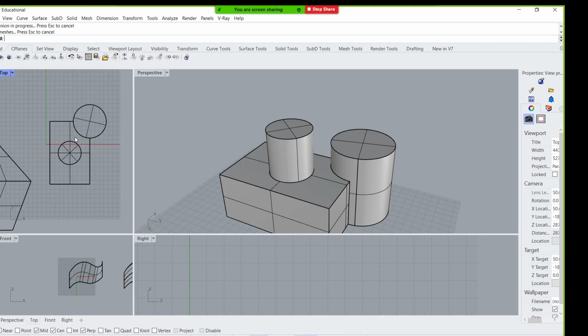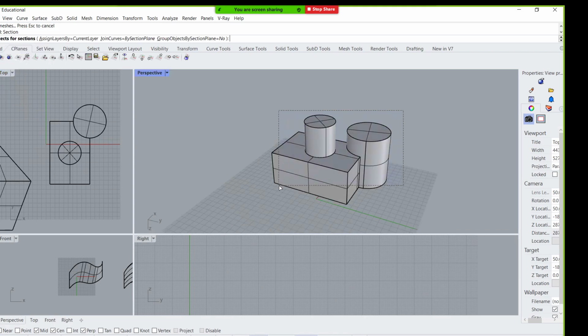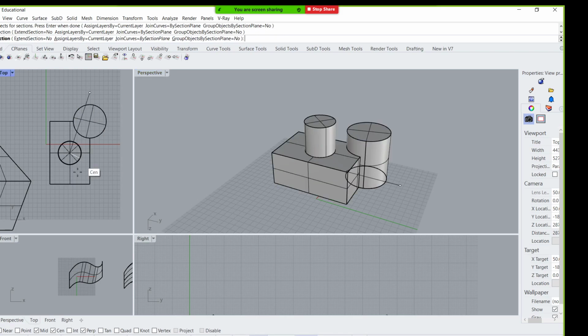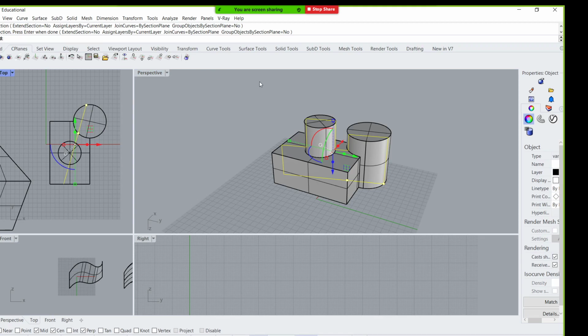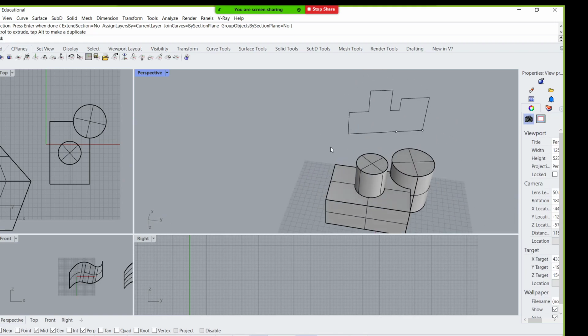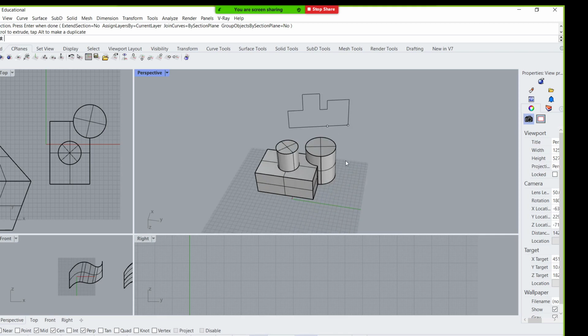I'm sure maybe you've used this before. Just called section, where you select. The first thing you do is select objects, hit enter, and then draw the start of your section line, the end of your section line, and you'll see that it has created basically a line that is a perfect section through that object, right? Pretty simple, this is a pretty simple object, so it's not that complicated. But if you modeled a whole building and you were trying to do a section cut that you wanted to manipulate, that could be pretty useful.